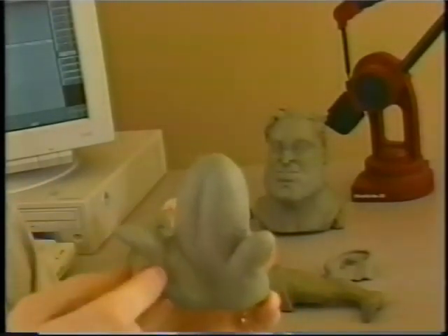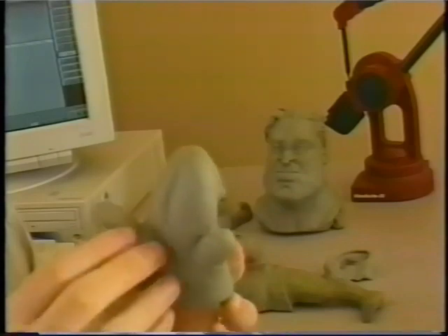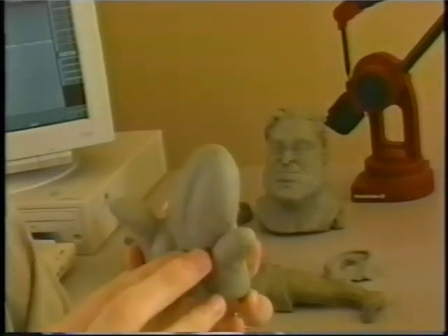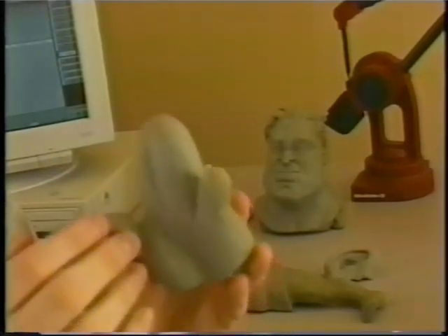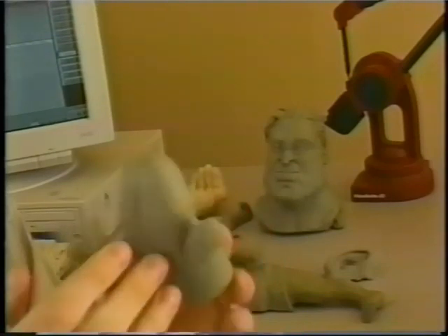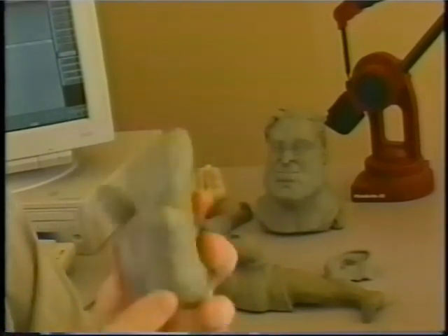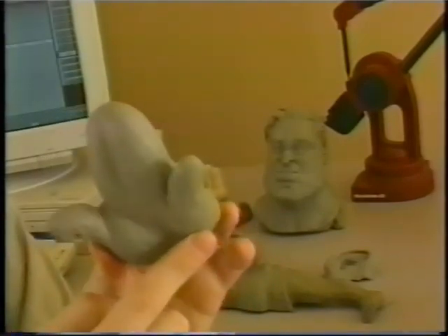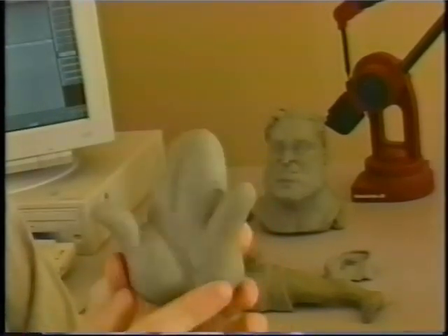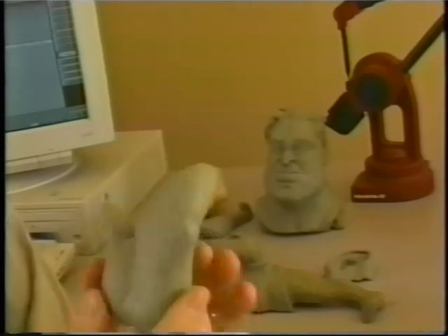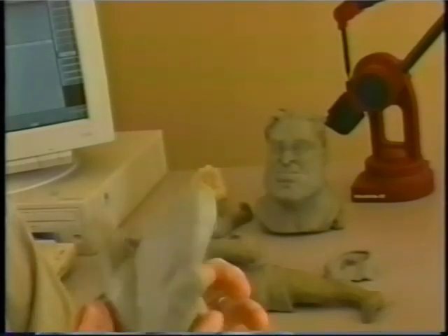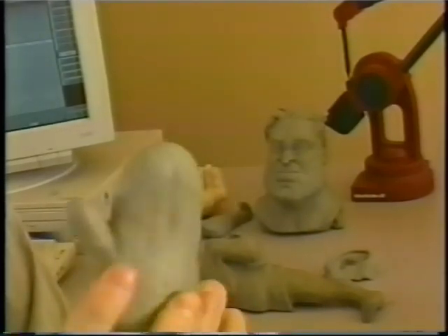So there's more lines going vertically along the thumb than you need because you have to have all that up here. But it makes for a very nice seamless connection. And the pinky can be attached with one of the surface connection techniques we'll talk about in a little bit. But that way you can get a very nice looking NURBS hand. You don't need to use quite so many points as you would with polygons.